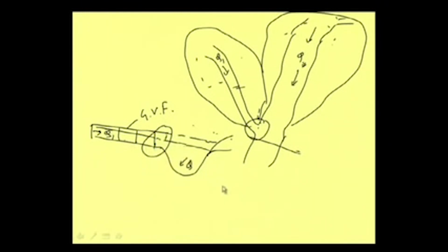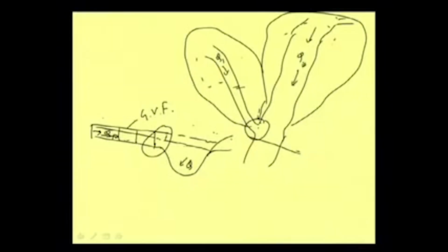So, the flow velocity in the tributary will be less. This can happen, suppose it is a river and it is a drain, then also this situation can happen. Then the flow velocity here will be less, meaning the channel will be carrying less water than it was carrying earlier because of the reduction in the energy level, and that sometimes can lead to flood congestion in the upstream area, here also in this channel.